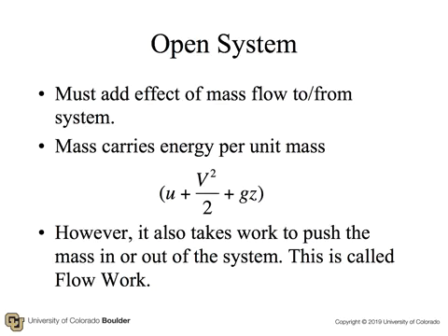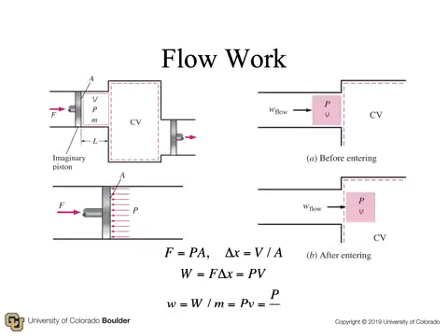For an open system, we must take into account the effect of mass flow into or out of the system. This is because mass carries energy in the form of internal, kinetic, and potential energy. However, it also takes work to push the mass in or out of the system. This is called flow work.